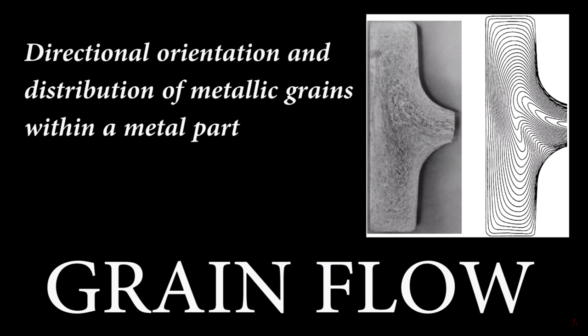Next, the grain flow is one of the methods to differentiate these 3 pistons. So what is grain flow? The grain flow is the directional orientation and distribution of metallic grains within a metal part. To make it short, the grain flow will determine how hard or how reliable the pistons are.